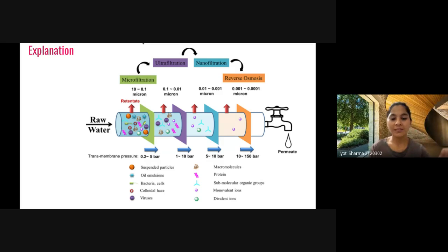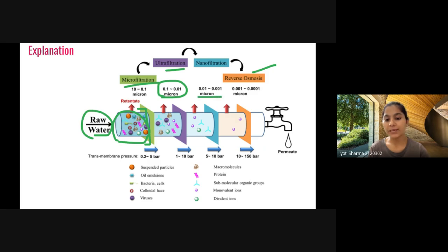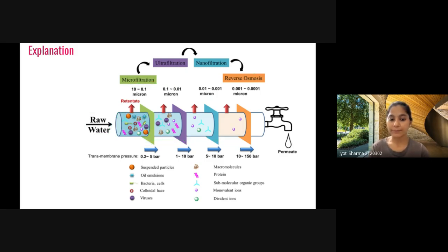Then this is a well known figure showing reverse osmosis and all. So we have some filtration. If we have raw material that may have a lot of contaminants, based on the filter size of your membrane, either it is microfilter or ultrafilter, we have a pore size. Based on that pore size, we can remove these contaminants easily. For example, we are using it in RO. So this will also come under physiochemical processes.